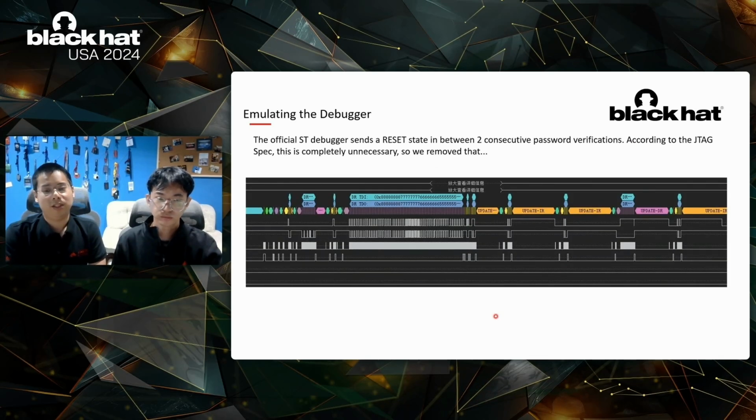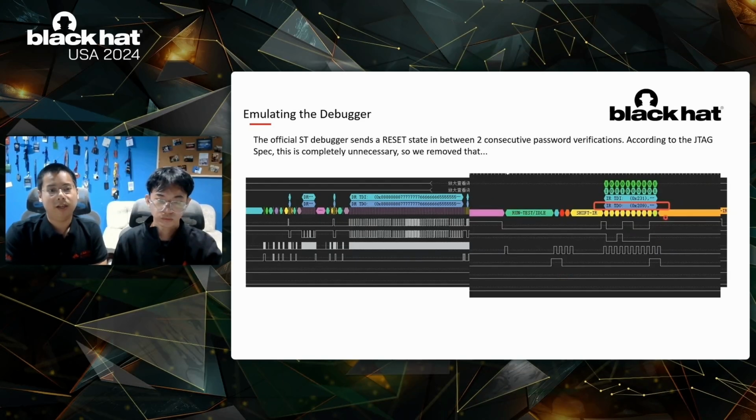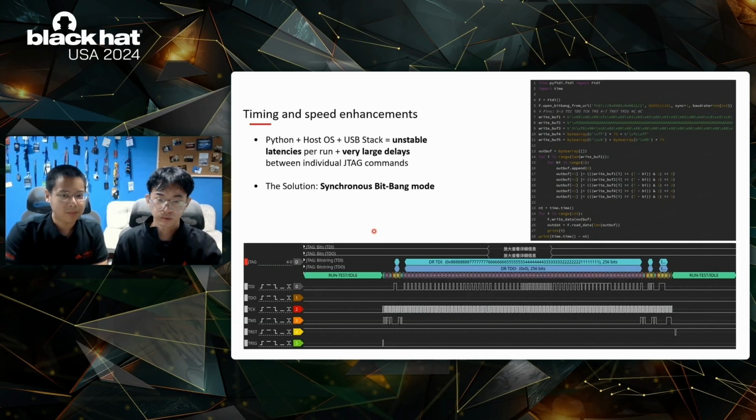This diagram illustrates the entire process of a JTAG challenge using an FTDI. The first successful attempt returns hex 201 after hex 2A, and hex 209 here after hex 3. With this, we have successfully bypassed the redundant authentication. However, there is an obvious issue. The delays caused by Python, the host OS, and the USB stack make the delay very inconsistent and large, such that a direct fault injection is impossible to align in time.